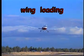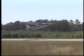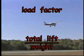I mean, there are several ratios that aircraft designers use to sort of score themselves on the design of the airplane. Wing loading, for example, is where you take the whole weight of the airplane and divide by the wing area that you see out here. And that gives you a sense of the relationship between the weight of the vehicle to how much area is supporting it. Another ratio that's very useful is the total lift efficiency or lift capability of the wing divided by the weight of the airplane. And that tells you how efficient of a lifting device the airplane is, and it also tells you how long the runway needs to be because it tells you how slowly you can land the airplane.